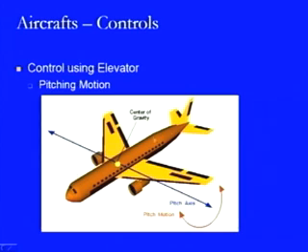So, that means the nose may go down or the nose may go up with respect to this axis. That is the pitching motion, and this is going to be controlled by these elevators being provided at this location. Again, these elevators work in a similar form as the rudder, and they are connected at this location, but at this location or at the ending location they are free. Therefore, these elevators can move up or go down with respect to the flat surface of this wing, and using this motion we can take the aircraft up or bring the aircraft down.